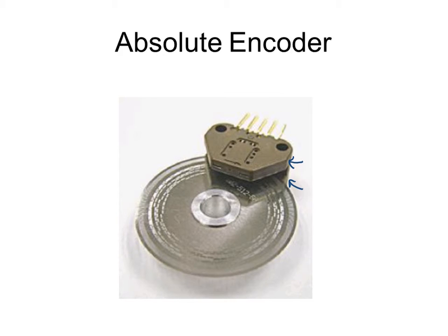It looks like, well, yes and no. We would have to see basically what that head has in it. We can't say it's 5 channel just because you have 5 pins, because when you hook up a light emitting diode, first of all, we can't put it directly across the line. I have to have power for the diode, and that's not a data pin. That's a power pin, right? And then I have to have this right here before I can do anything.